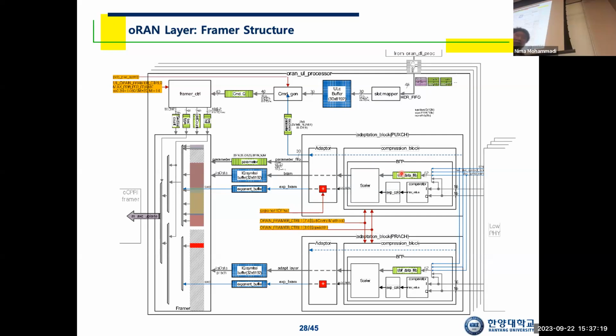Here we are talking about uplink, so ORU will send the packet to the ODU. Then, similarly, when ODU receives this packet, it will perform the deframing procedure, mapping the packet values back to the original OFDM sample positions, and ODU will perform the high-PHY procedures, okay?